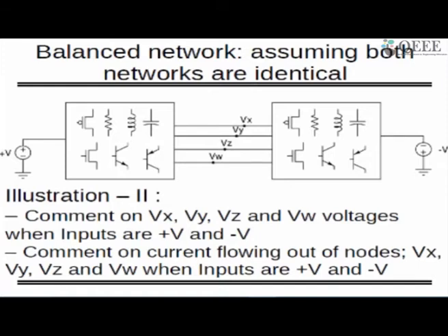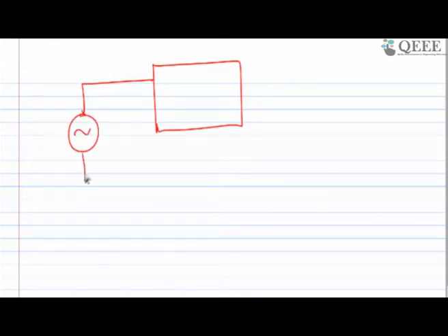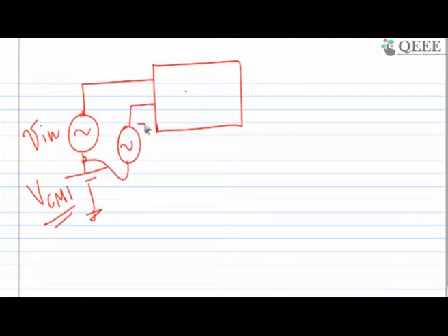When I was trying to understand circuits, this was the better idea to understand. Let's say you have two balanced networks. Before telling this I should say that any circuit I am going to use will have two things, one sine and one DC. DC is common mode. The common mode input voltage takes care that the BJTs in this circuit will be in the active region of operation. That can only be done by the input common mode voltage. Inputs are the ones going this way, or you can say 180-degree phase shifted, and I am taking the output from this side.